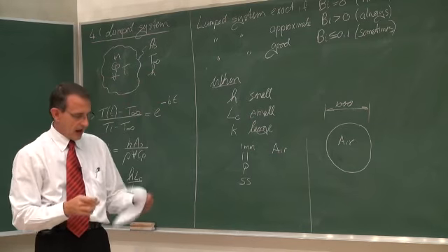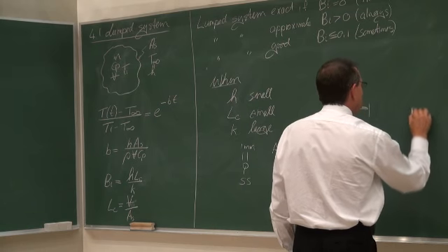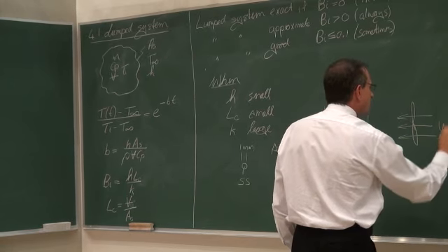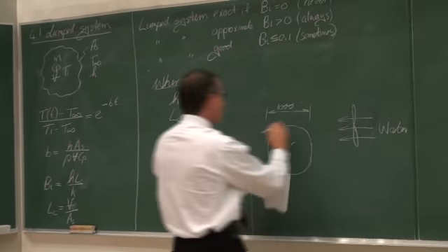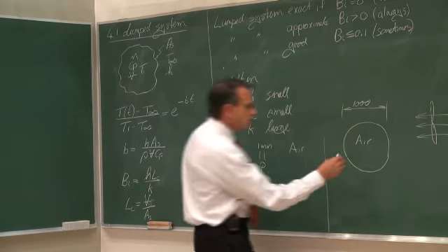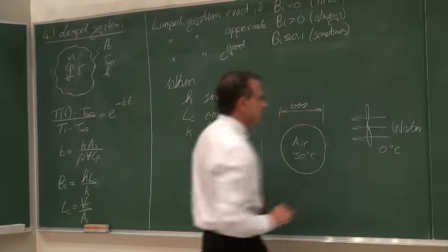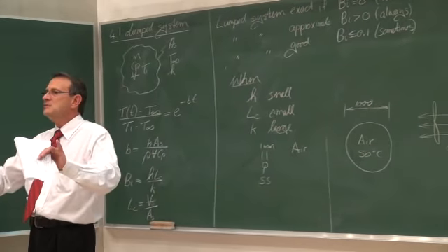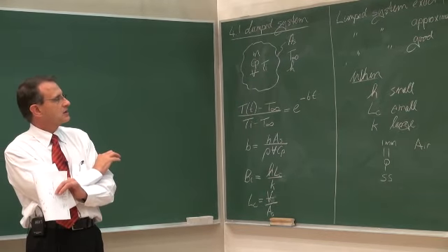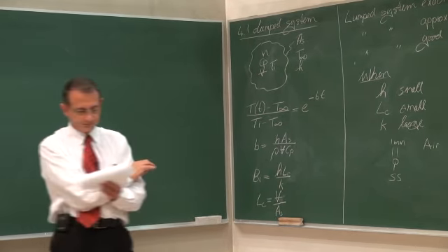And this is going to be thrown into something with water, where this water is circulated around the ball. Let's suppose the ball temperature has been increased to 50 degrees Celsius, and this water temperature is 0 degrees Celsius. So two extremes in terms of what we can consider as possible good or bad candidates for a lump system approach.